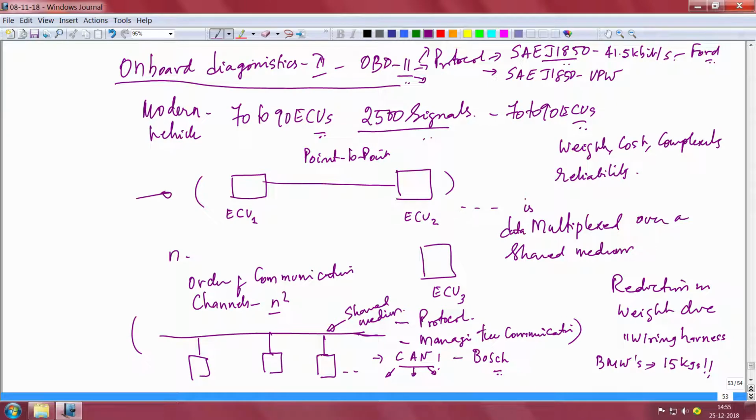Before we move on to further parts of this module, it is good to sort of understand the OBD2 protocol and the variants of them quite well. One of the first things that you will see when you read up on OBD2 is SAE J1850, there is an extension called PWM, okay. This gives you a data rate of 41.5 kilobits per second, standardized by Ford.